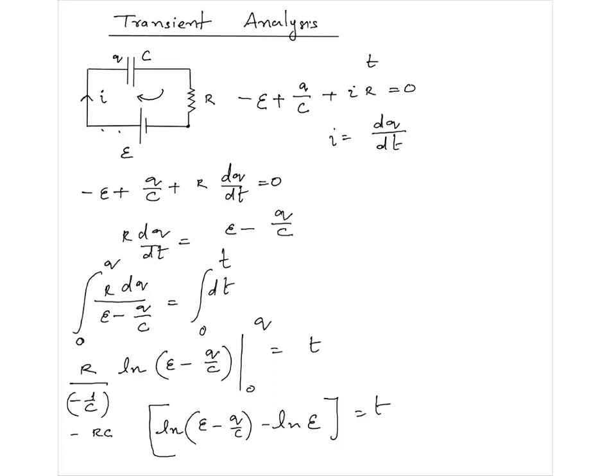So the conclusion is that the capacitor behaves as short circuit at t equal to 0. Short circuit means you have two plates. Imagine two plates are connected by a nice conducting wire, straight. That's the meaning of short circuit. You have 2 points, you connect those 2 points by a nice conductor. That's the meaning of short circuit. So capacitor is short circuit at t equal to 0.